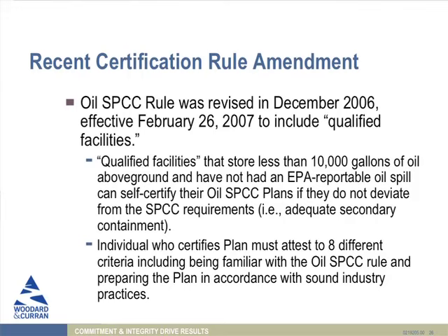You are a qualified facility if you store less than 10,000 gallons above ground and you have not had a reportable release of oil. What that means to you is that if you can meet these criteria, you could essentially self-certify your SPCC plan. You don't necessarily have to go to a registered PE. I caution you, if you do though, you have to attest to 8 different criteria if you are self-certifying your own SPCC plan. Among them, that you're familiar with the SPCC rule and you've prepared the plan in accordance with good industry practice. If you don't know a lot about that kind of thing, you're probably better off having a PE certify your plan for you.